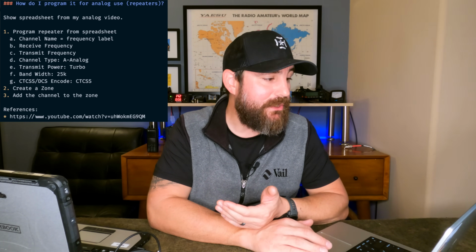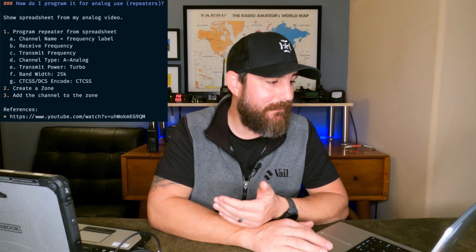So in terms of things that you need to have at your disposal, it is the channel name, or what I used to call the frequency label, the receive and transmit frequency, the channel type, we set that to analog. The transmit power for that channel, I typically set mine to high most of the time. The bandwidth, so with analog radio, we always use 25 kilohertz. With DMR, per the specification, we're actually only using 12.5 kilohertz, exactly half. It's a lot more efficient in terms of the bandwidth.